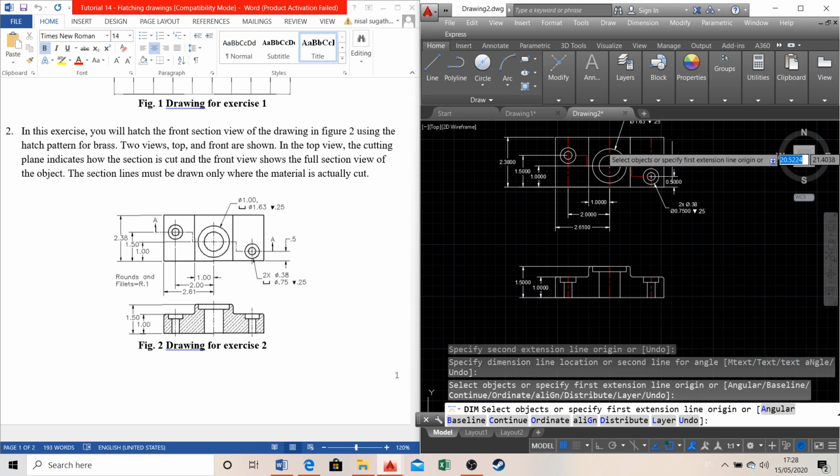So like I said before, this view is basically the cross section view that runs along this center line. Okay, so it's not actually in one plane, it runs along 2-3 different planes, and that's the front view that we have here. So normally when you get a cross sectional view, to represent the solid parts that are running along this plane, that's basically this initial part, and then you have this part, and you have this line, this, this, and this. So to represent those parts, we need to show in our diagram that these are solid components.